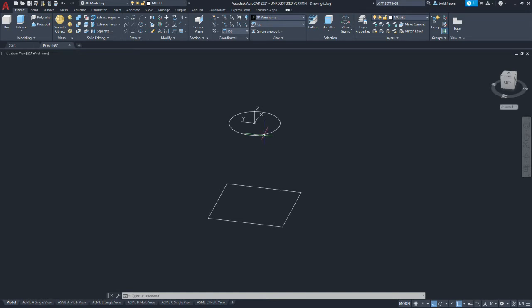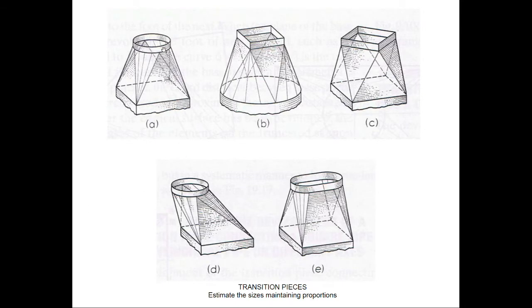Now we have a flange on the top. I'm going to show you 2 ways to do this part, and the first one is actually going to be technically somewhat wrong, and then we're going to come back and do it correctly. The reason is I want to show you the difference between the lofts. So we're going to create another circle that's going to be the transition for the flange. It will represent the distance between where this curvature ends and where the duct splices into another duct.